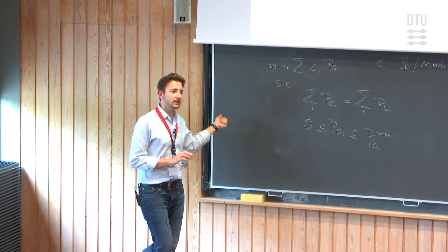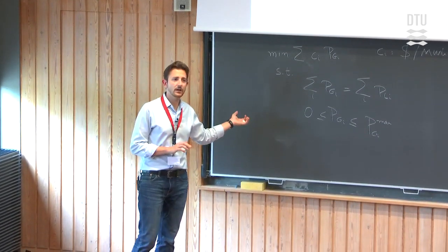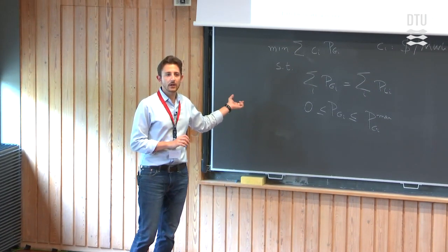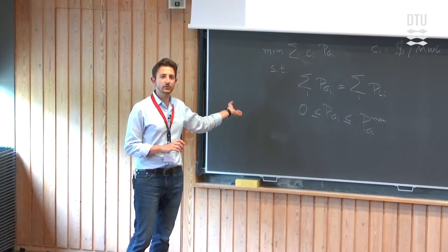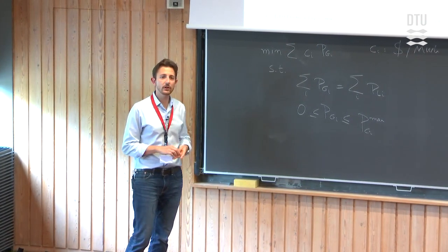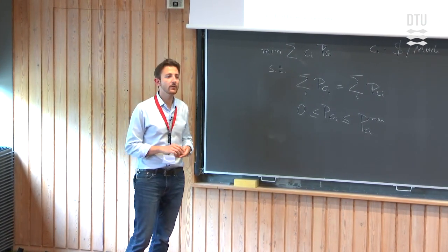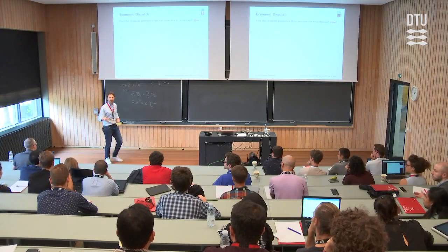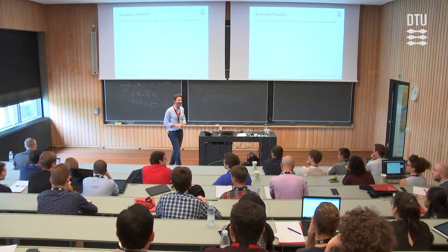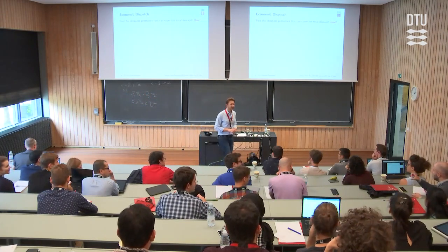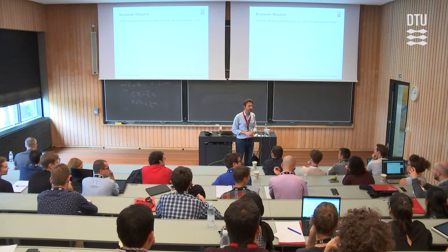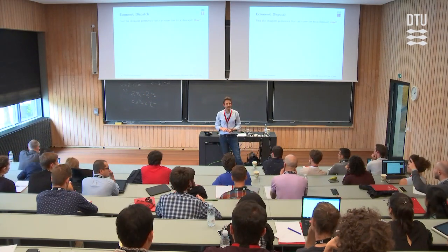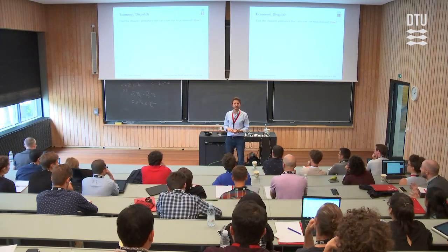Can I solve that? Is this clear? Any questions? Can I solve that without actually optimizing, so without using a solver? How? Complementary modeling. That's too advanced. No. You take the cheapest generating block, you fill part of the load, then you take the second one, you fill part of it, and the remainder. Great. It's separation. Everybody agrees?